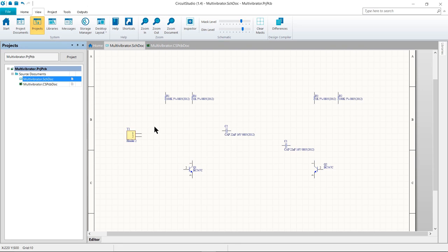And we have now placed all of the components. Note that the components shown in the image of the schematic are spaced so that there's plenty of room to wire each component pin. If you do need to move a component, as with any placed object, just simply left-click and hold on the body of a component and then drag the mouse to reposition it and then let it go. So next up, we'll begin wiring up the circuit.